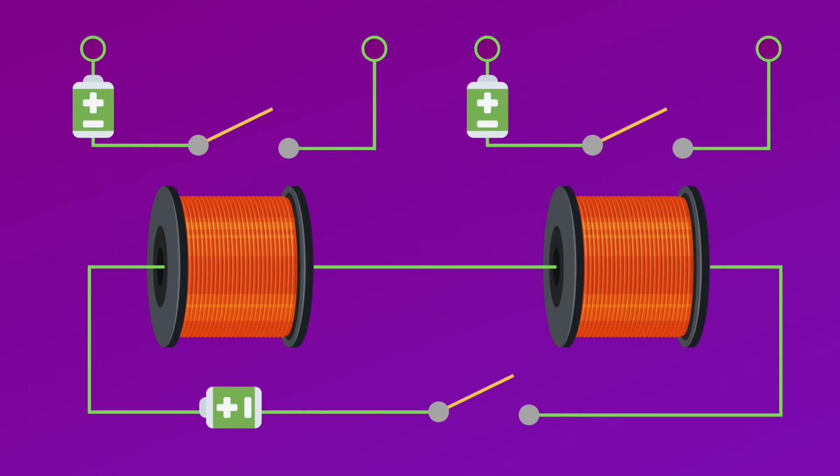Now let's talk about how relays can be used. The first way is that relays can actuate multiple circuits while only using a mechanical switch. What I mean is that one mechanical switch can turn on a circuit that actuates two or more relays. Each relay then actuates the circuit. Therefore, you can easily turn on multiple circuits at the same time by using relays.